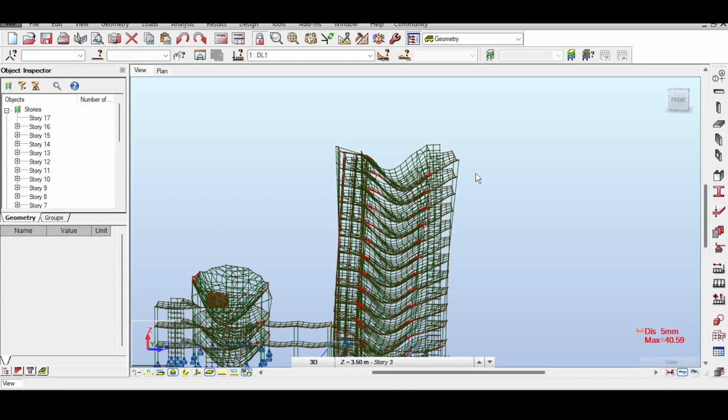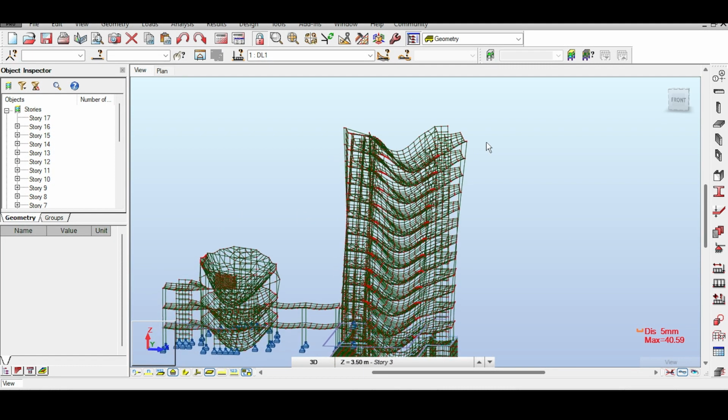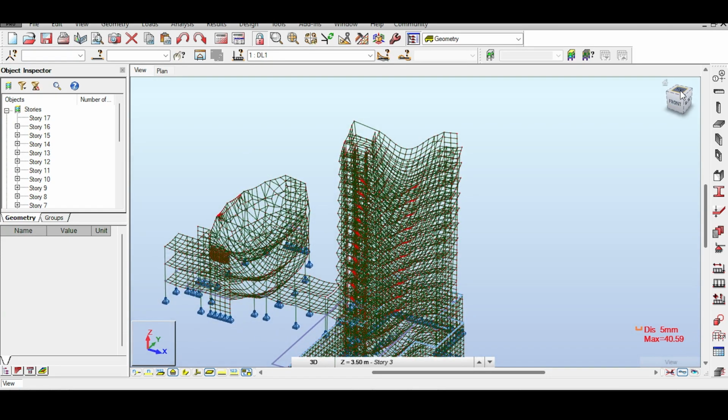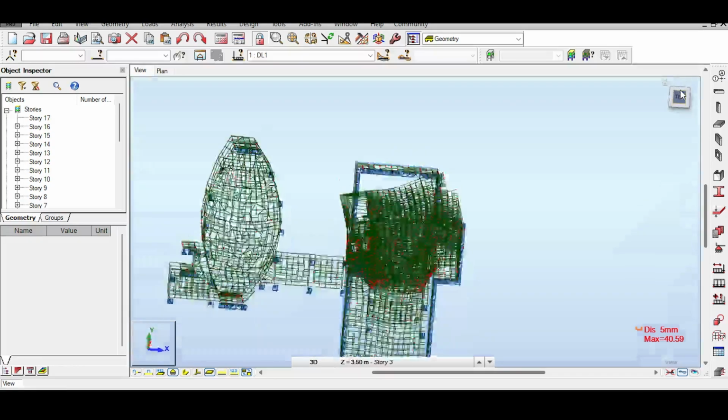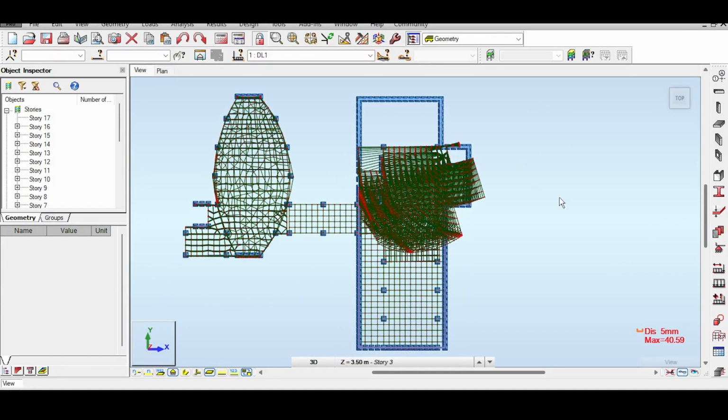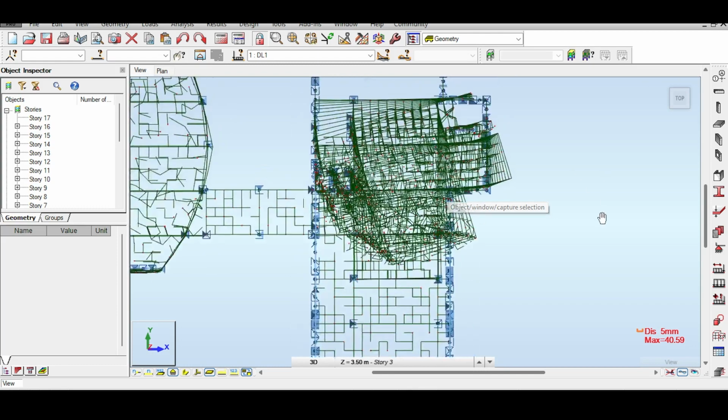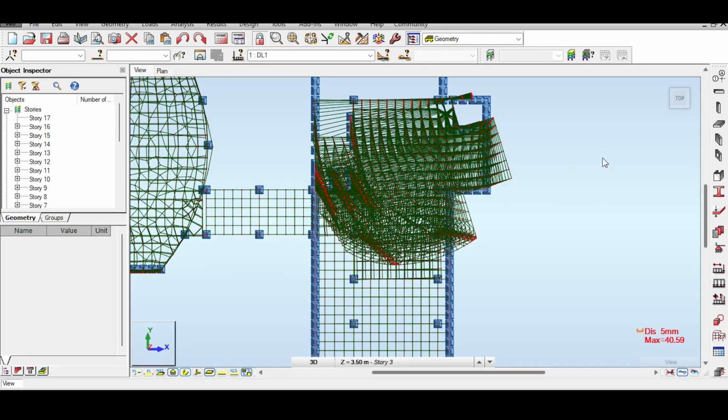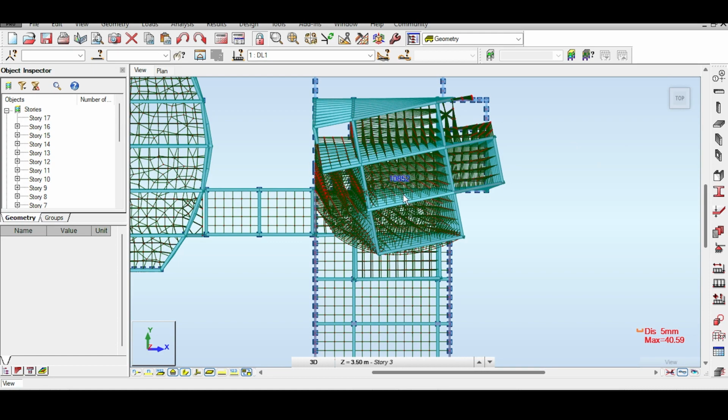Okay, so continuing our efforts, and this is day 2 because on the last day I actually recorded this beam thing, the problem with the beams, and now we are back to continue the problem with the twisting of the structure. So to understand where exactly the problem is, of course, I had a previous video, and I think I linked it in the beginning of the video, where I was talking about how unsymmetric supports could cause the structure to twist under its dead load. And if you open the sections, you can see that, well, it just happens to be that.